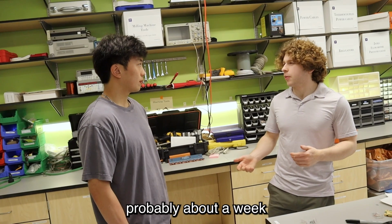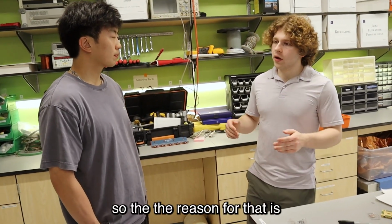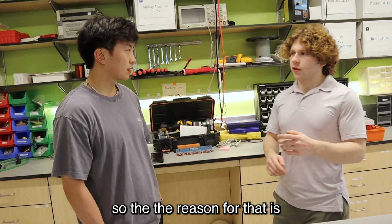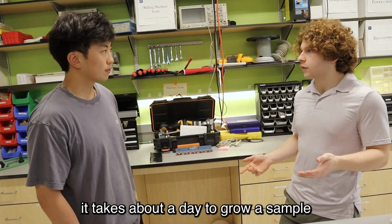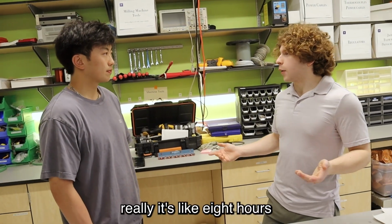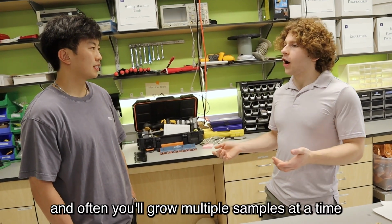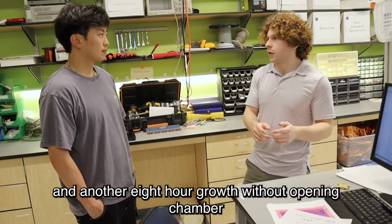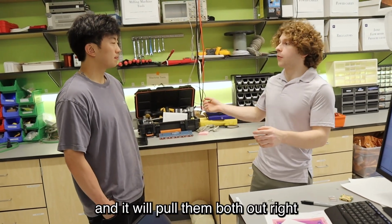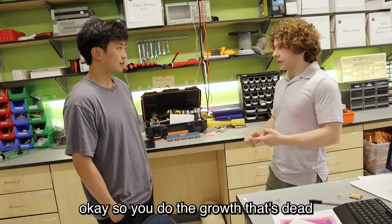But realistically, probably about a week. But you can do multiple chips in parallel. The reason for that is the molecular beam epitaxy growth takes a long time. It takes about a day to grow a sample. Really, it's like 8 hours, but people aren't going to be growing for 24 hours. And often you'll grow multiple samples at a time. So you'll do an 8-hour growth and then another 8-hour growth without opening the chamber, and then you'll pull them both out. Okay. So you do the growth, that's a day.